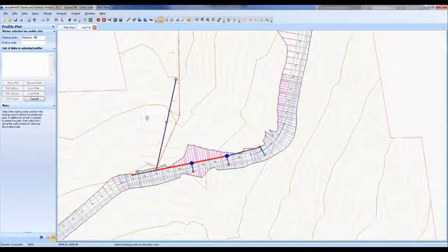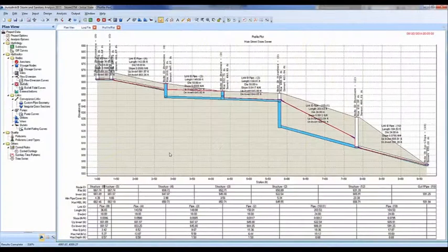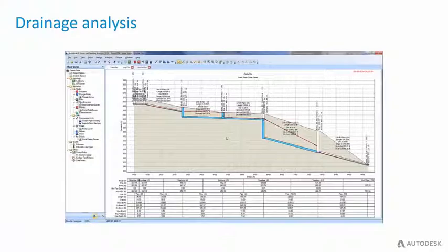But I would like to see it in profile view. So let's say, okay, now I'm interested in this path. So I selected the start point, end point, and I have here my profile view, including, you can see this blue color is the level of the water, and you can see that in these two manholes there is surcharge because it's too small to accommodate. So if I specify, for example, 20 years water, because again it's up to me, intensity, how much, and so on. And this is definable, and the system will tell me, okay, this is too much.